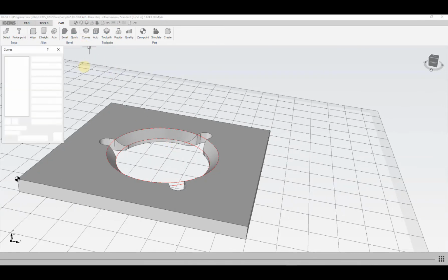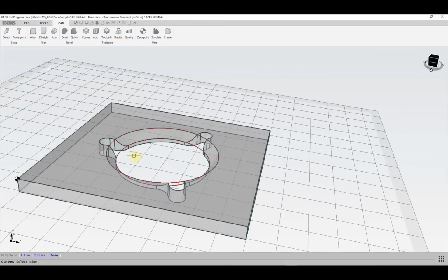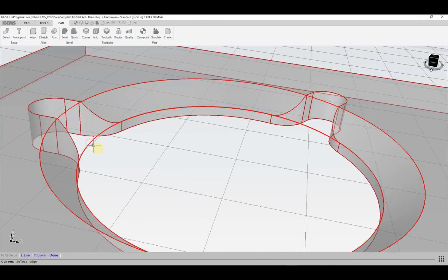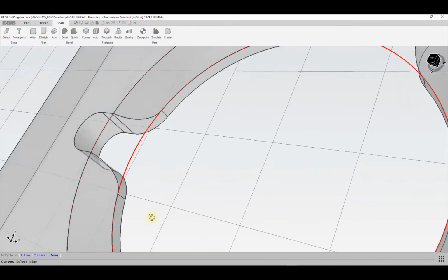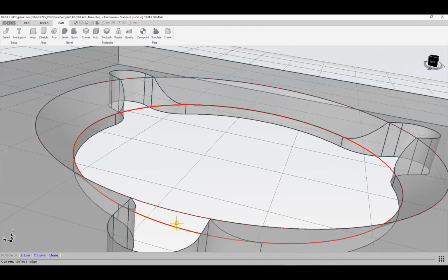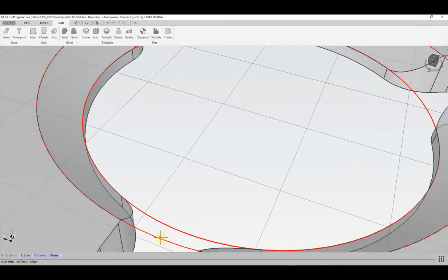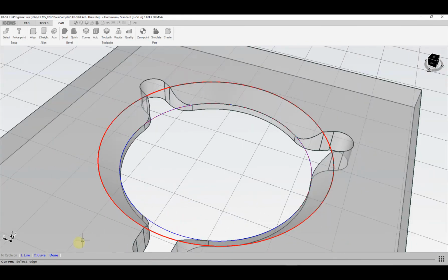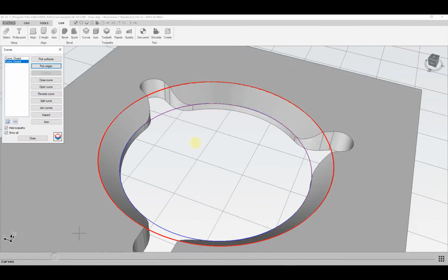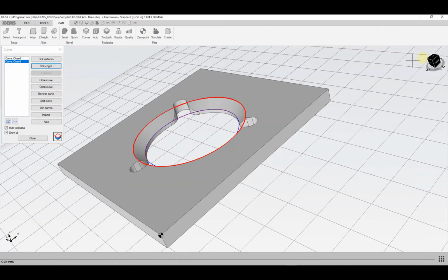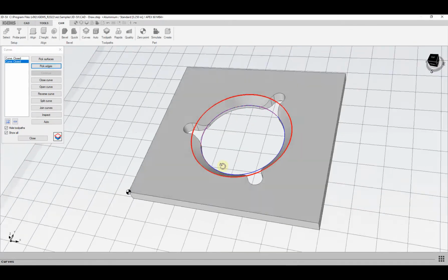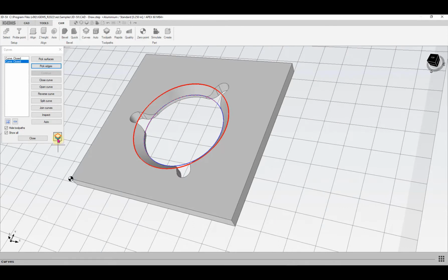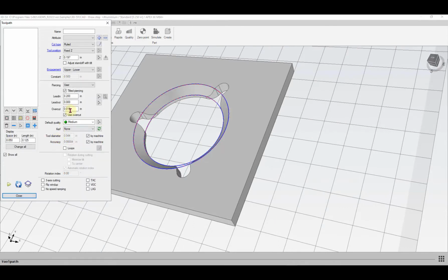And then we'll go ahead and click curves and pick edges, and we'll choose that as one edge, and then we'll choose this as the other edge that we need for right now. We'll come back and do the vertical cuts later. So now I've got that, can go to our toolpath area and see what we got for settings here from before.